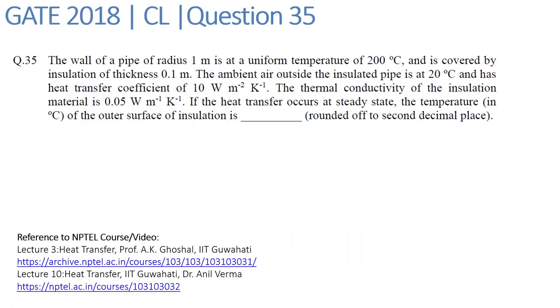We looked upon the solution of this question, in which we had to write the heat balance and consider the resistance, convective and conductive resistance. And ultimately we find out the temperature at the outer surface of the insulation.